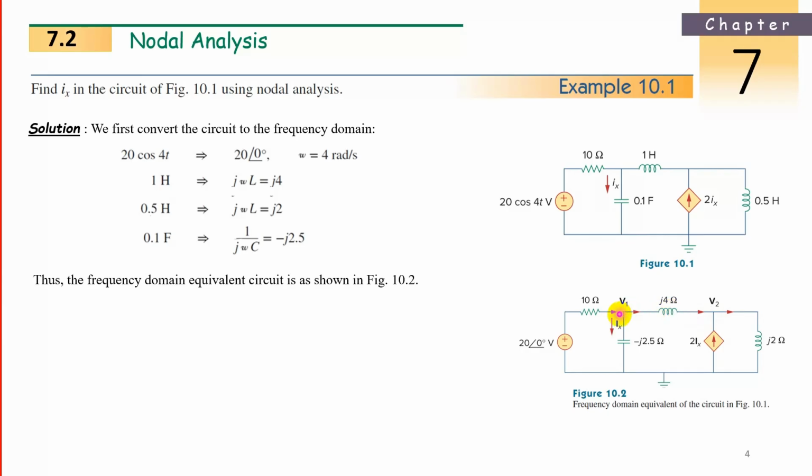Now for the remaining one, since it is leaving from here, you cannot assume it is also leaving from the other node, because it leaves one node and should join here. So the current is joining at this node, meaning entering. Now two entering currents are there, as per our experience. Two entering, so one should be leaving, right? Everything cannot be entering the node. So two are already entering, so one I can assume as leaving. So I mark it as leaving there.